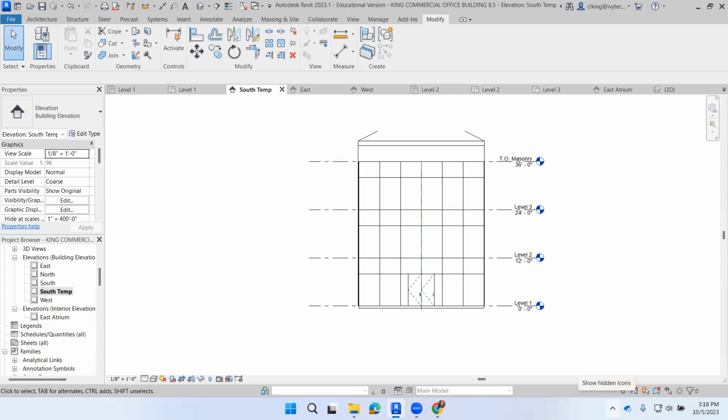Now I am on page 8-20, adding curtain wall mullions. This far you have simply set up the spacing for the curtain wall mullions. Next, you add to place the curtain wall mullions. This involves selecting a size for the mullions as they typically come in many shapes and sizes. The depth is usually related to the height of the curtain wall, as the mullions act as a structure for the glass wall. Switch to 3D view.